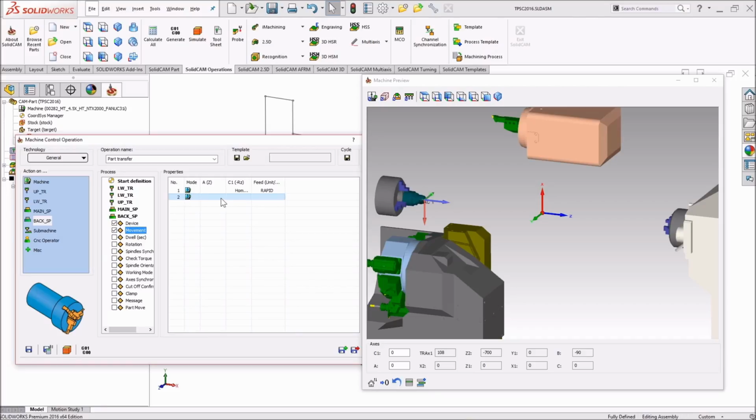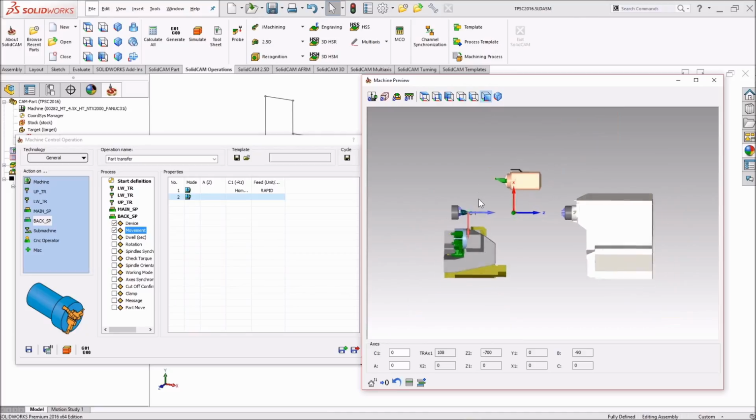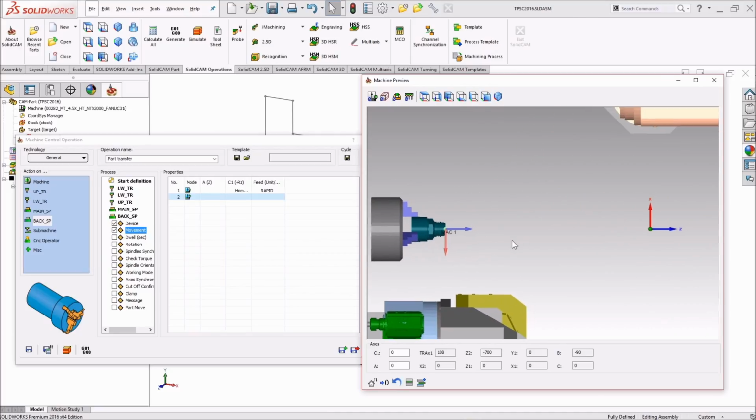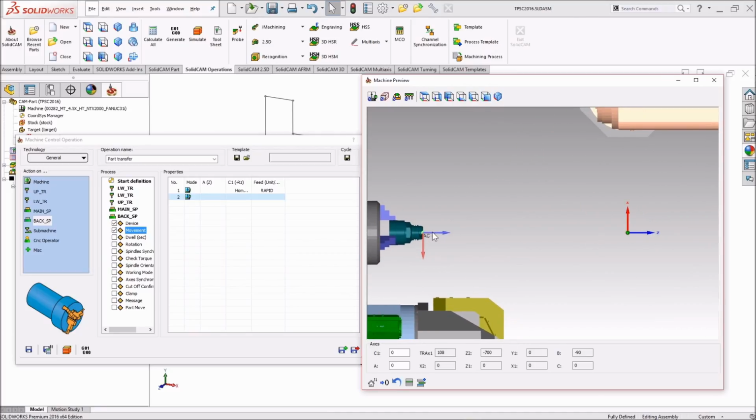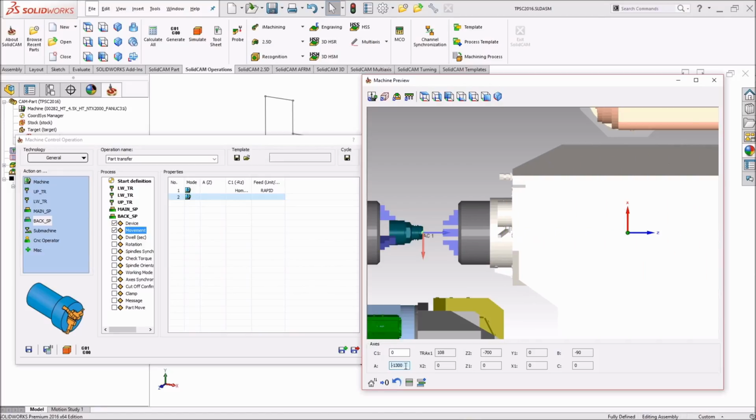The very first thing I'm going to do is go to my front view, and what I would like to do is move my back spindle as close as possible with the rapid motion, let's say to the same safety position. How I do it is up to you. I'll use my scroll button, and let me put in 50. I think it will be fine, and save. So I'll put 1350 on my A, and I'll make paste axis values.